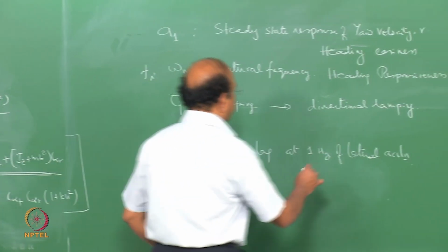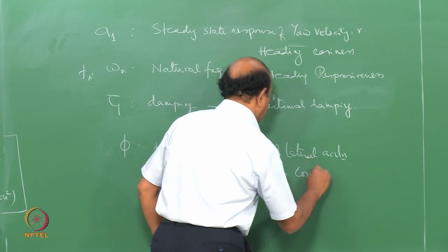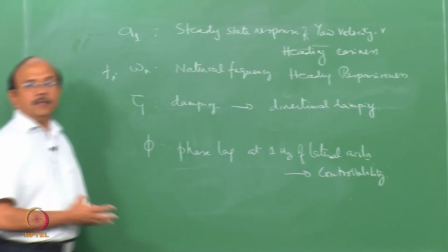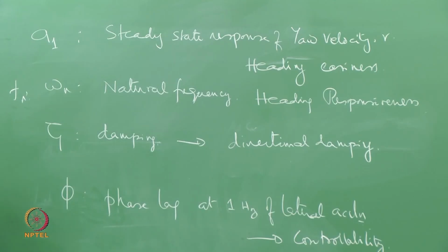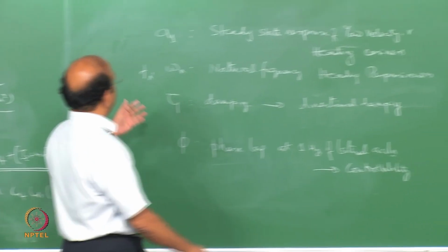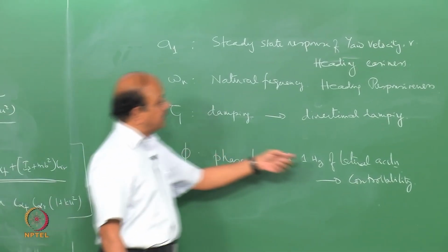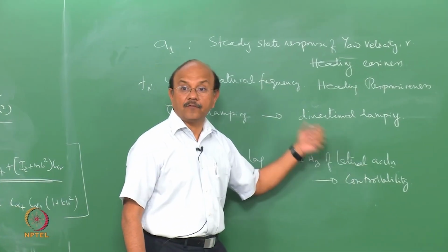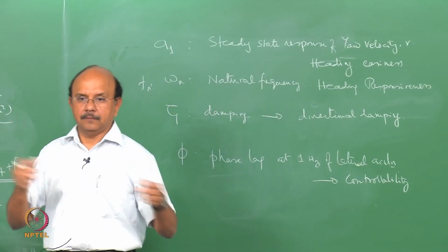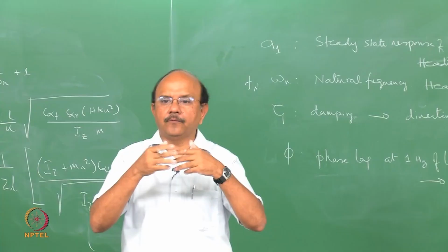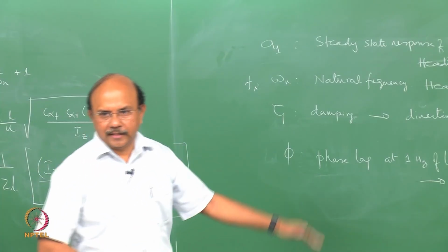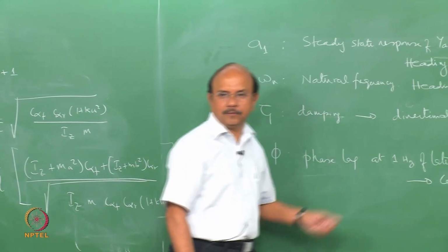Right? So these are the 4, yes. Is there a correlation between the phase lag and natural frequency? No, this is for lateral acceleration. Phase lag of lateral. So how do I find this out? Remember we had the transfer function yesterday. In that transfer function we have to substitute S is equal to j omega, and then you would get that at 1 hertz, and that's what you would get.